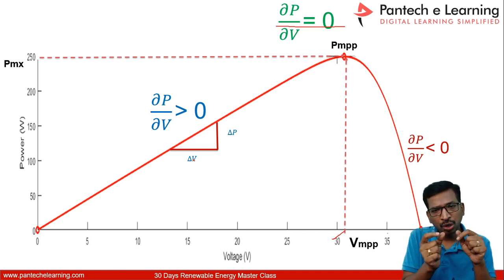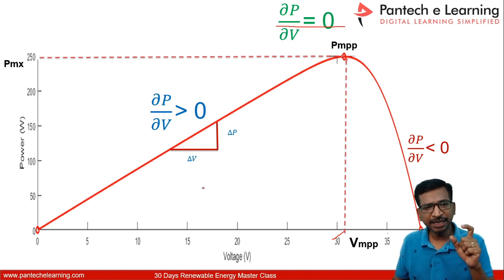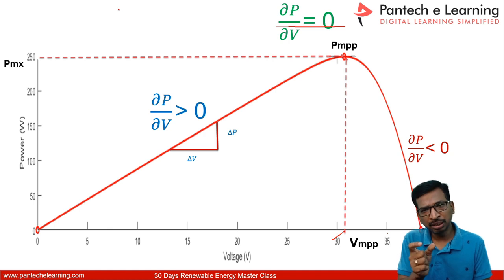So now you have an option to vary the sample time. If you take any one sample, then the next sample will be based on that sample time interval. If you take the voltage at the nth interval and the voltage at the n minus 1 interval and calculate the difference between the two intervals, that is called the rate of change of voltage.